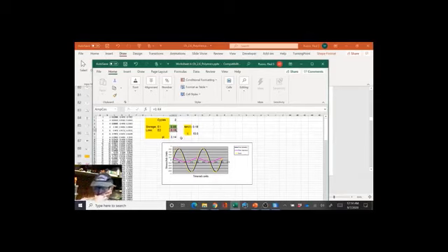Okay? So now we see that the sum in yellow is tracking more closely to the sinusoidal in-phase term, which is the elastic thing, which let's say that's the sine term. If the gamma strain is a sine, then d gamma dt, or gamma dot, is a cosine, right?